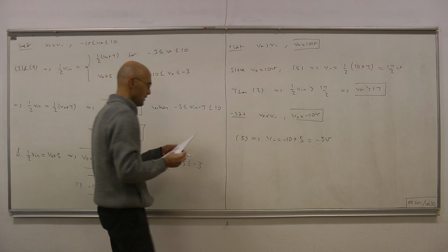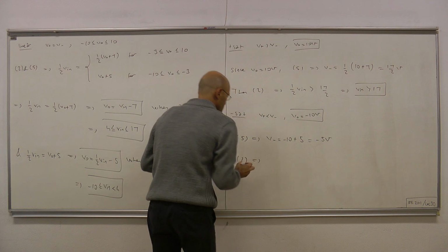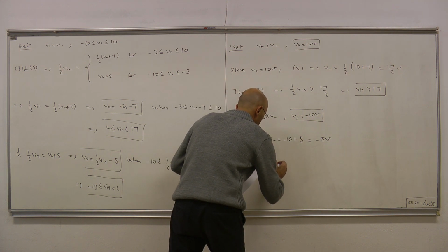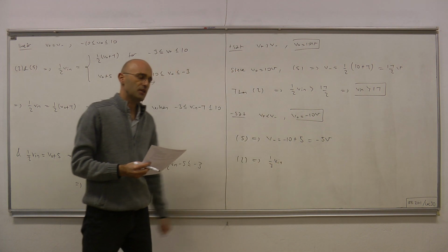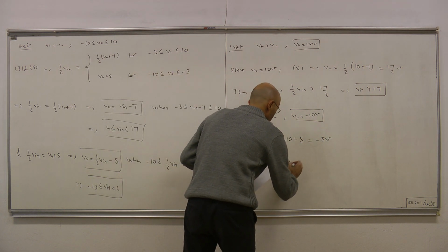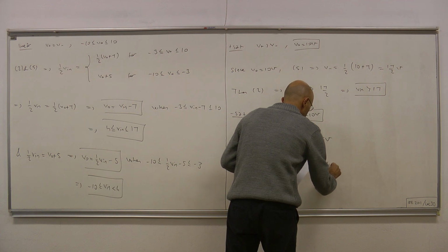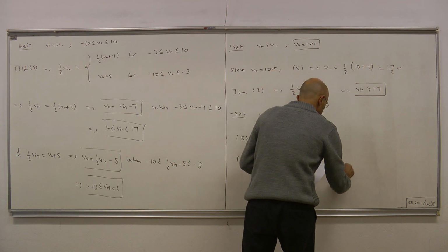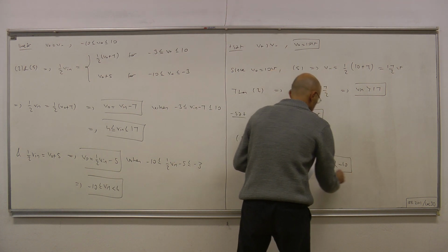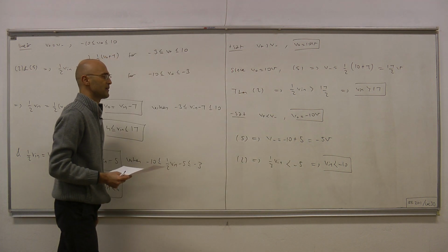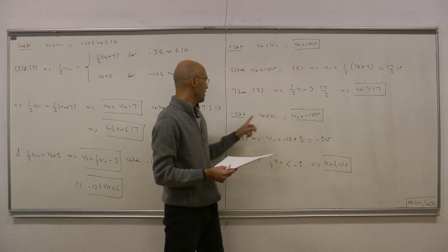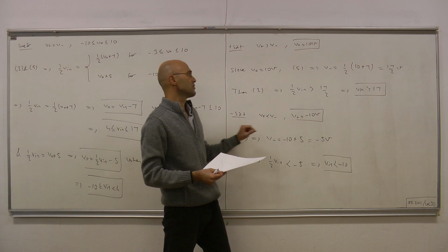Okay, and then 2 once again implies 1/2 V in, which is V plus, less than V minus, which is minus 5. Implies that V in less than minus 10 volts. Okay, so when V in is less than minus 10, op-amp is in negative saturation region.